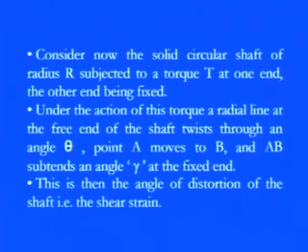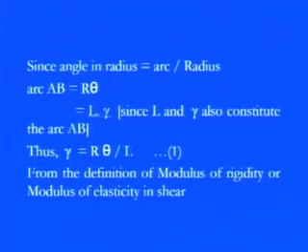And if you are taking the substantial amount of this twisting, we are always measuring a kind of distortion as far as the total length L is concerned, so this is coming as gamma, that is the total distortion. So we can say the angle of distortion of the shaft all along the line is always the shear strain. Now we would like to set up the relationship between the applied torque and all those things. So here you just go to the basic part: at the extreme free end corner, there is a twisting from O to A to O to B.